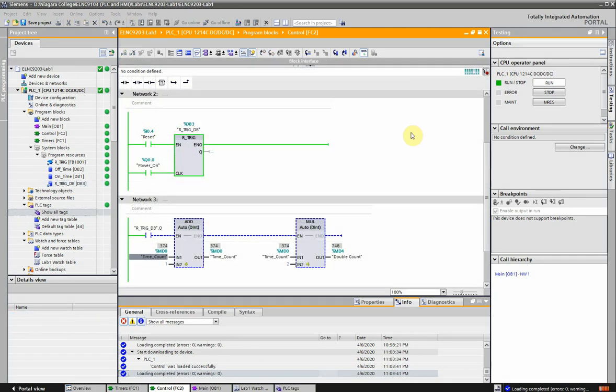Okay, I want to show you another thing here. Maybe you've heard of temporary words that can be used inside a program, and I want to demonstrate one way to not use those temporary words and talk about how to use them properly. Temporary words are used within the local function and only inside that function. They can't go outside the function unless you send it out through a global data word or a global word.